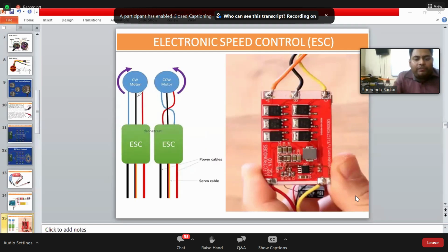First of all, if you want to make the direction of the motor clockwise, you have to connect all the wires sequentially, one by one, directly to the ESC without any interchange. There is a trick while we are connecting these wires. Always remember, connect the middle wire of the motor and the middle wire of the ESC first. Okay, you just put the middle wires first. Why? So that you can decide the rotation of the motor.